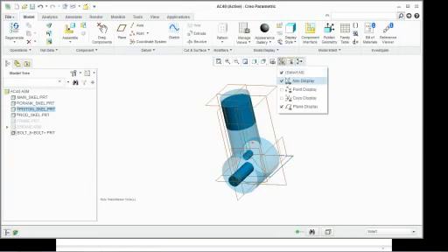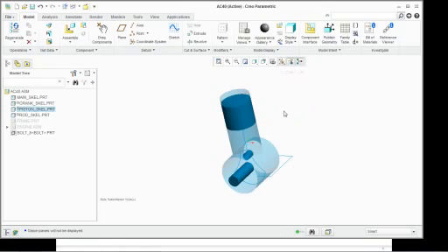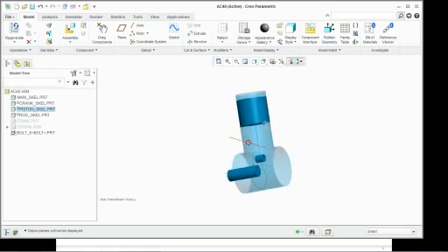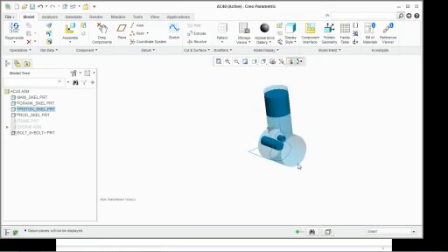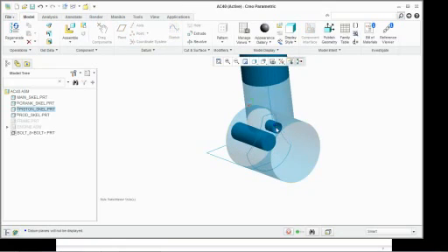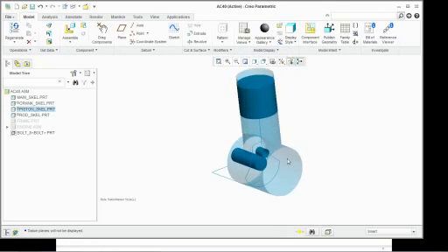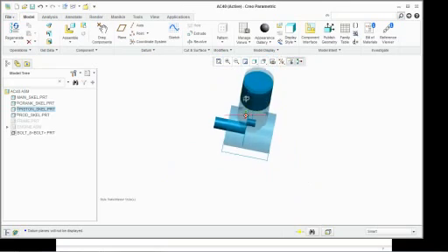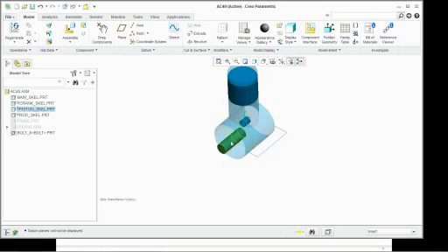So now I'm going to turn my planes off, my axes off, so you guys can see I've got a skeleton that's a realistic representation of an engine that we're going to build, and I can come in here and actually drag it through its full range of motion, and it will function the way that the final engine will. But I don't need to know all of the details of how parametrically to create the piston or the crankshaft or the rod. I just need to know roughly their lengths, that sort of thing, and I can create my assembly from this.